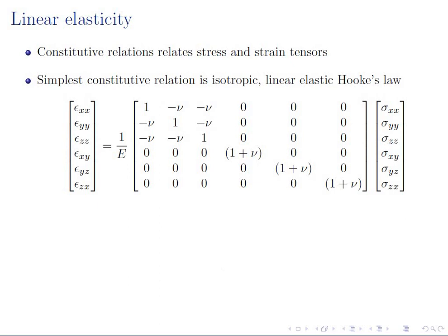So now we have the complete definitions of stresses. We know what stresses are, we know what displacements are, and we also know the relationship between the strains and the displacements. The next thing we need is the constitutive relation, the relations which describe the relationship between the stresses and the strains. For this particular course, we will use Hooke's law. We will assume a linear relationship between the stresses and the strains, and Hooke's law in 3 dimensions looks like this form, where this is the compliance matrix.